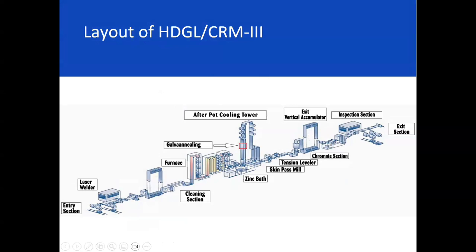The part from the entry looper to the exit looper we call the process section. For every coil, there will be coils finishing at the entry and coils unloaded at the exit. During these stoppages at the entry and exit sections, the process should not stop. The basic idea is to run the process continuously. For that, this looper houses half a kilometer of coil.